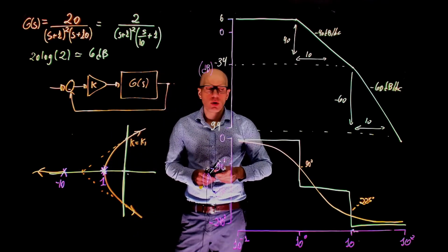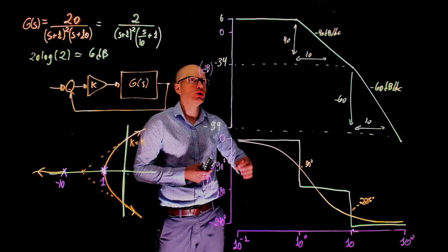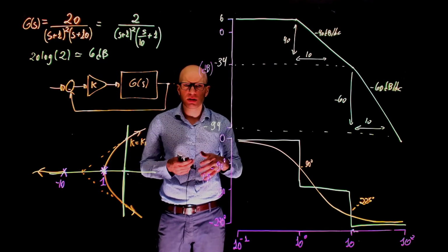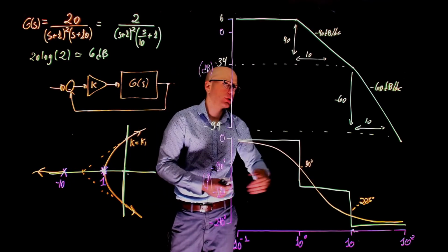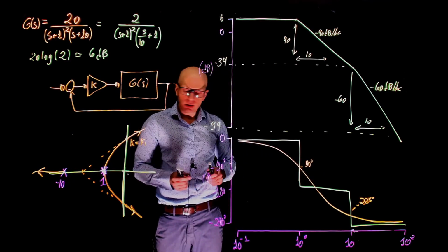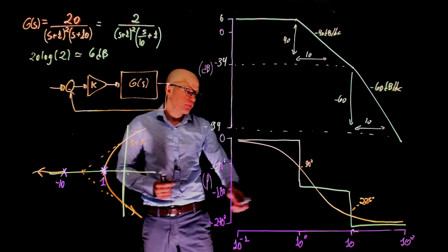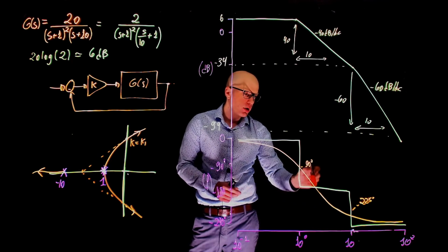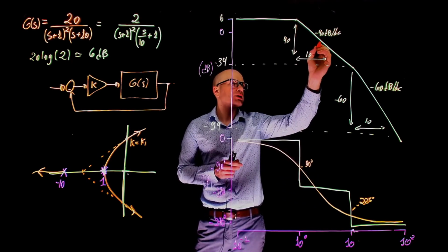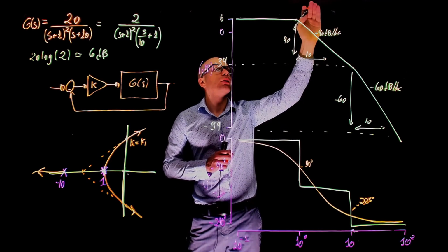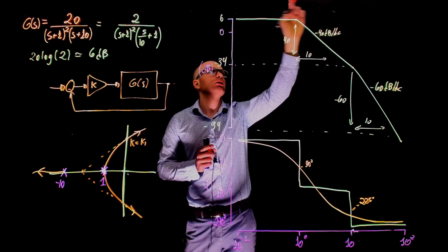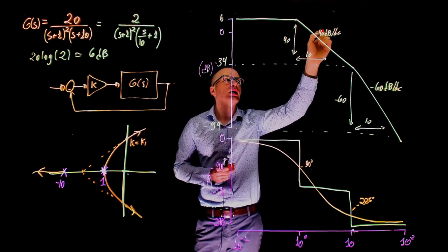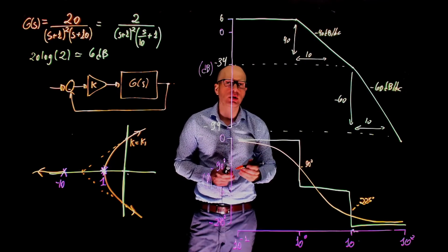on the Bode plot? On the Bode plot, we should see the perfect combination of 0 decibels and 180 degrees of phase. The system is marginally stable here, should be marginally stable there. It is very likely that when we reach this value of k, we are looking at this specific point here, 180 degrees of phase shift. If you go up, the Bode plot that is now here will be shifted up by a certain amount. We're looking at a Bode plot like that, and we'll be crossing 0 decibels exactly at 180 degrees of phase